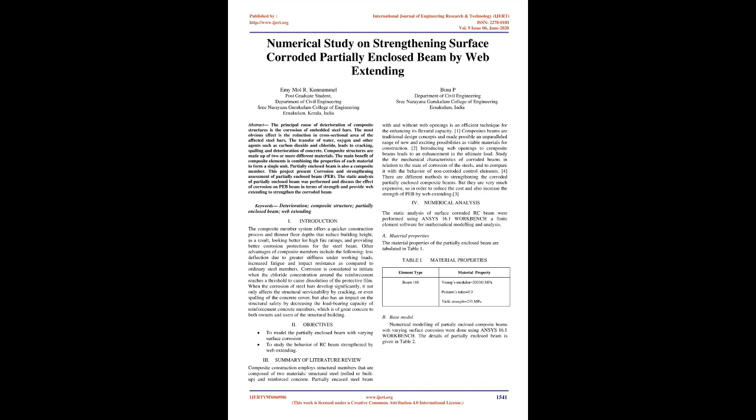Corrosion is considered to initiate when the chloride concentration around the reinforcement reaches a threshold to cause dissolution of the protective film. When the corrosion of steel bars develops significantly, it not only affects the structural serviceability by cracking, or even spalling of the concrete cover, but also has an impact on the structural safety by decreasing the load-bearing capacity of reinforced concrete members, which is of great concern to both owners and users of the structural building.